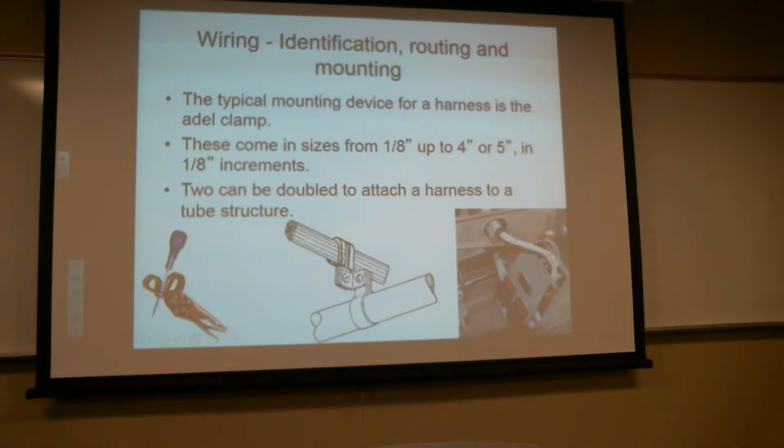The double attaching is actually kind of useful. Aircraft Spruce makes a set of vice grip pliers with these 2 little clamps welded onto it. You take an awl and run it all the way through, and then 2 clamps come down, clamp it down, and hold it all in place. Pull the awl out, put your hardware in there, get it started, then release it.